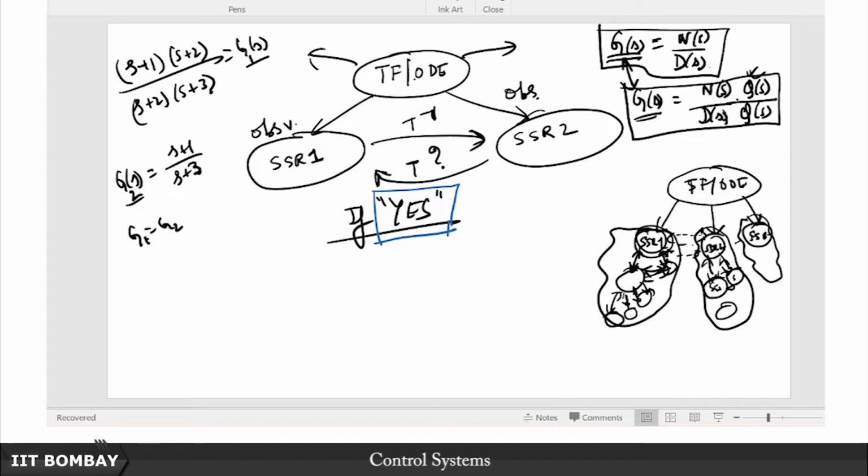But for the purpose of realization they are not the same. When we are talking about realizing a transfer function, we are disallowing this sort of equality. We want equality in every sense. So the degree of the denominator polynomial, the poles, the degree of the numerator, the zeros, they must all be identical.